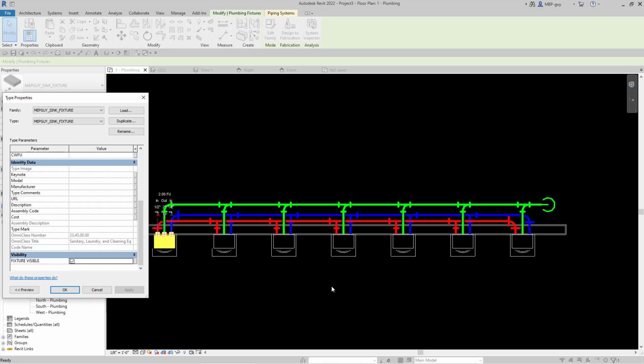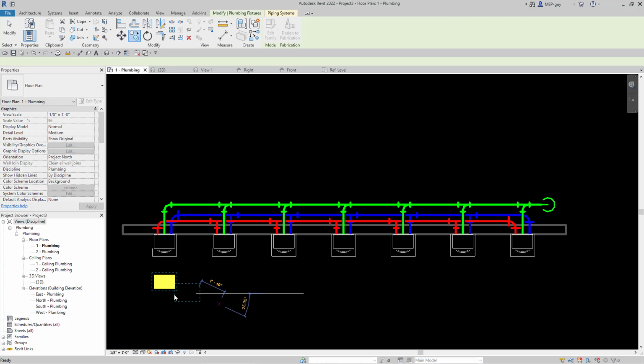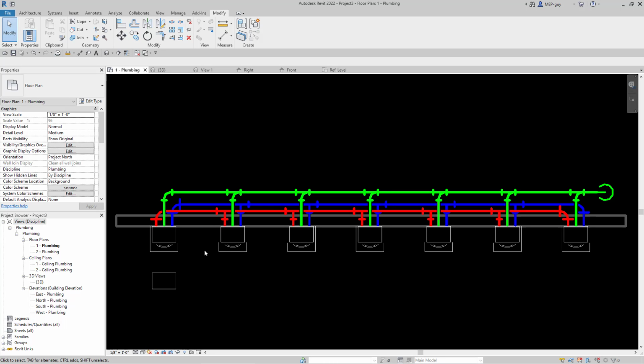Okay, there's a lot of different ways, and I've shown them in other videos, so you can do whatever method you like best. Now the last thing I will mention is, let me go ahead and just copy one of these fixtures. And one thing I don't know if I talked about is these fixtures are actually what we call non-hosted. They don't host to anything like the walls or anything like that. And that's extremely important, because you're going to run into a lot of times where the architect decides to delete this wall right here. And if you're hosting your fixtures to this wall, all of your fixtures are going to not know what to do, and you're going to get all these warnings.